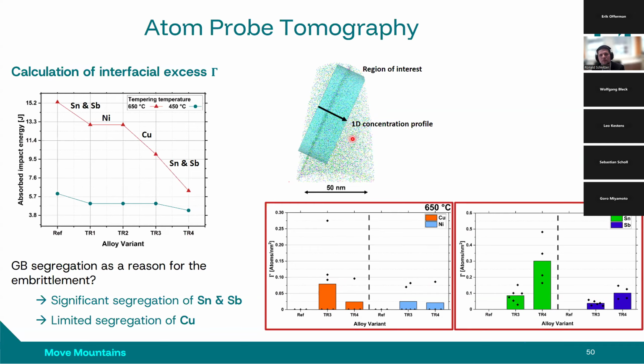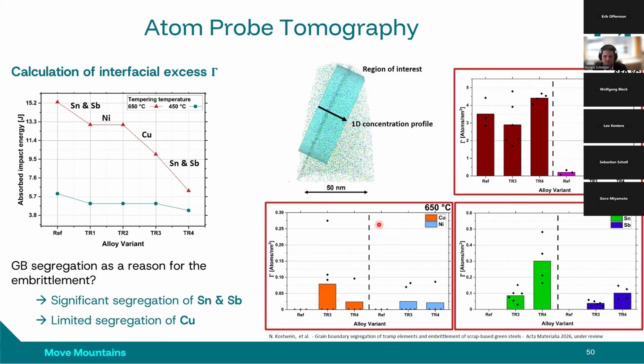And what is important to mention here, you can imagine that, or you know that atom probe tomography is very time consuming, and evaluation is always not that straightforward, but anyhow, any measured dot here represents one APT measurement. So that means a lot of data were generated in the sense of APT, which is a very local method. But when one takes the average values, one can see this increase in these different elements. And also for carbon, carbon is well known to segregate to grain boundaries, atoms per square nanometer on grain boundaries for carbon. And here you can see it for phosphorus.